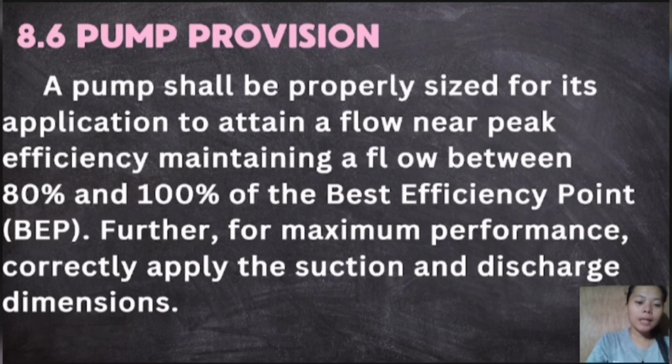Pumps are correctly operated near their best efficiency point or BEP. This is where pumps work the most. For proper pump size, keep efficiency between 80% and 100% of BEP, and use correct suction and discharge pipe dimension. Why this is important? Because it prevents